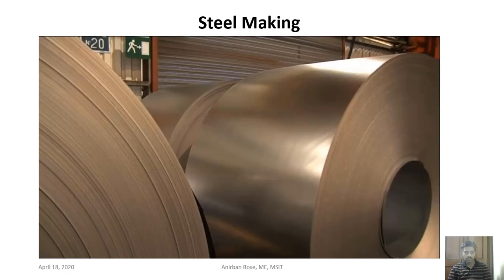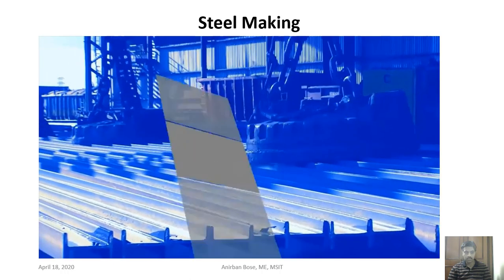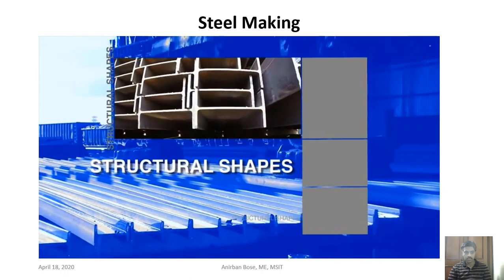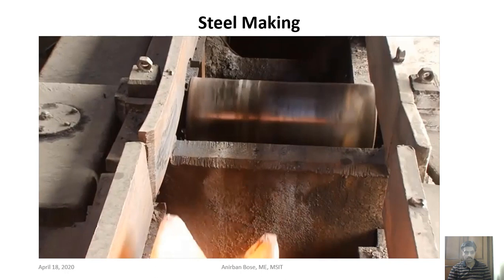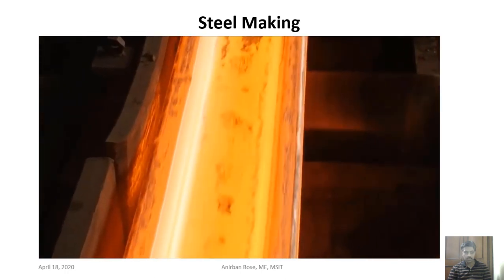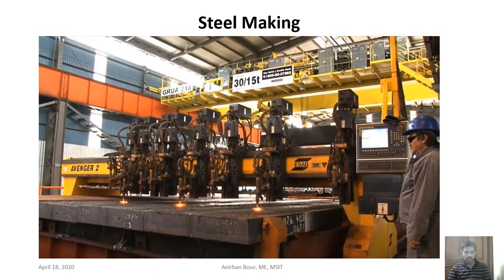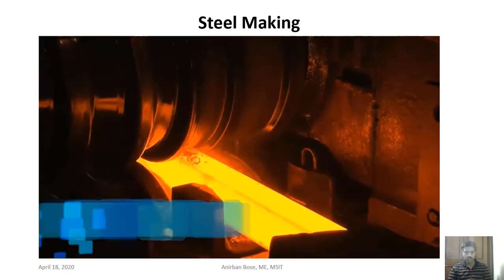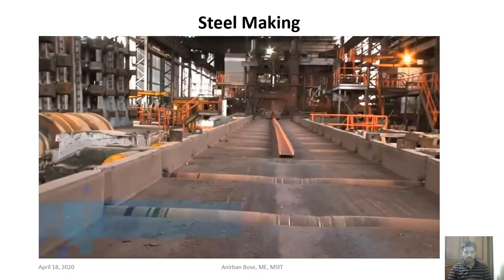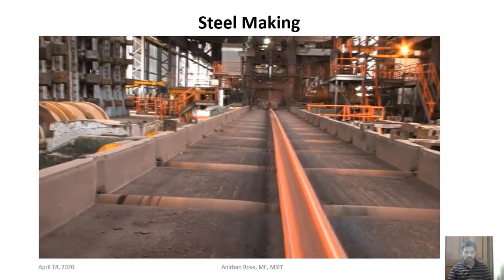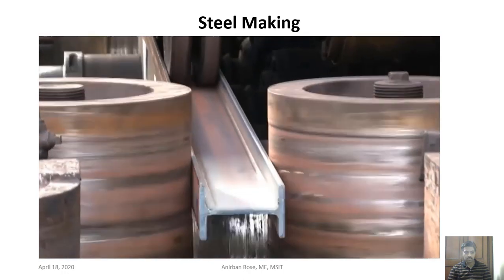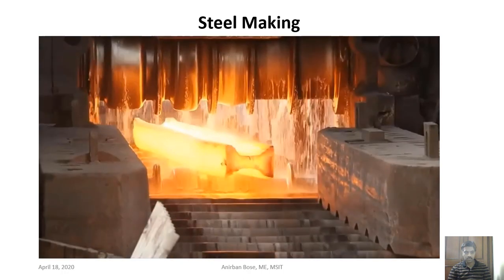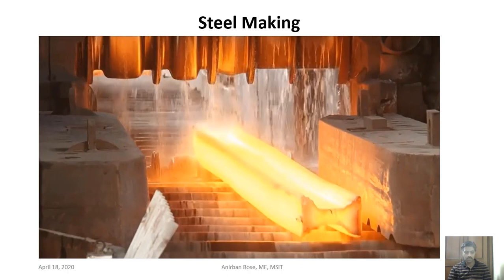In addition to the hot rolling and cold rolling lines, there is a department of structural shapes. AMSA is the primary domestic manufacturer of structural steel for the construction industry. Production begins with the cutting of the steel slab into square pieces called blooms. Reheated in an oven at over 1,250 degrees Celsius, the blooms go through various rolling mill trains to produce structural shapes such as W-shapes, C-shapes, and angled L-shapes.